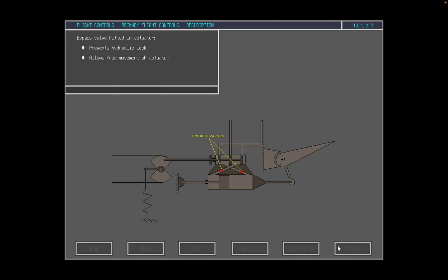Bypass valves are fitted in the actuators to prevent hydraulic lock should the actuators become depressurized. This arrangement ensures control is always maintained. If the pilot valve jams, a detent assembly switch detects the problem the next time a control input is attempted. This causes the bypass valves to open. A shut-off valve located upline of the actuator closes to remove hydraulic pressure if the system is turned off. The bypass valves open automatically to prevent hydraulic lock.